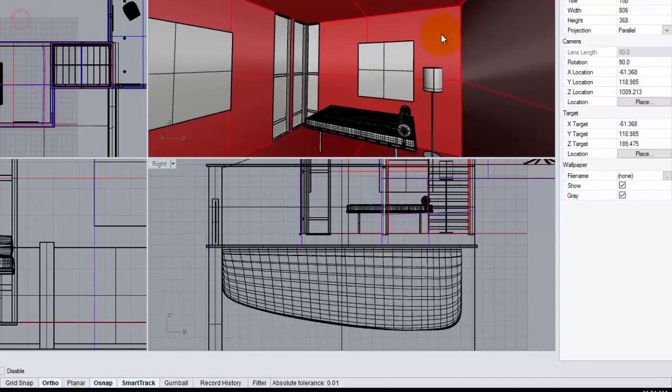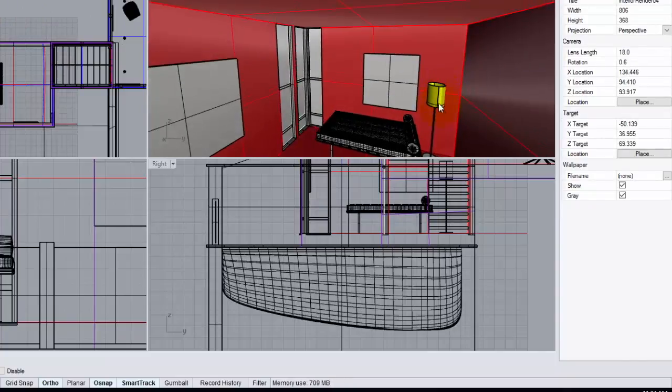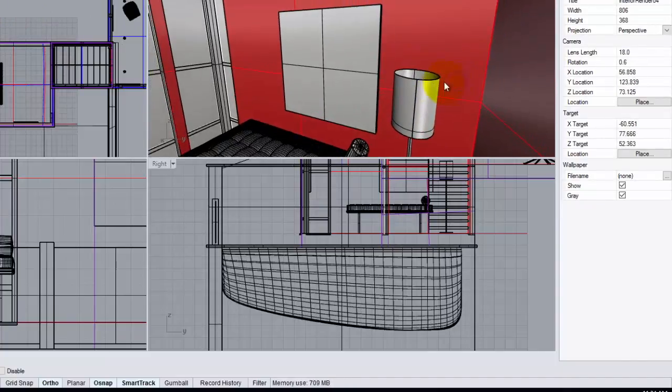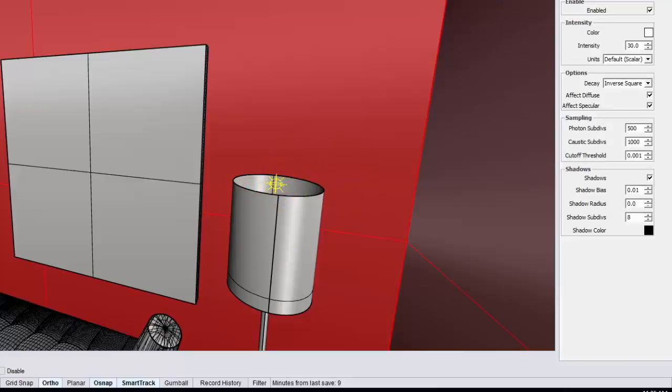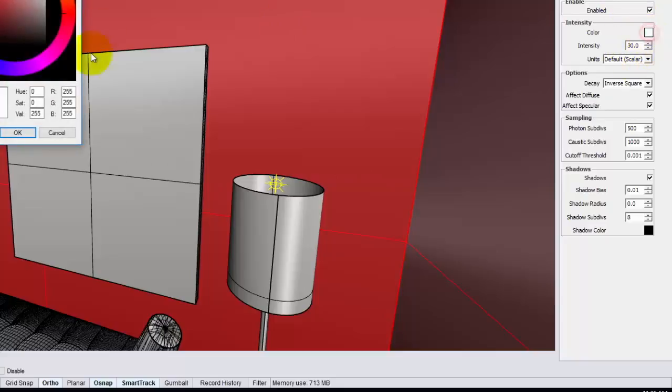I need to install the point light into this light. So let's look right at the center there. And I'm going to create a point light this time. So let's go to the point light. We'll snap it right to the center of this light fixture. There it is. Let's edit our properties. So with it selected, I come over. We'll start with the color, 255, 214, 170.